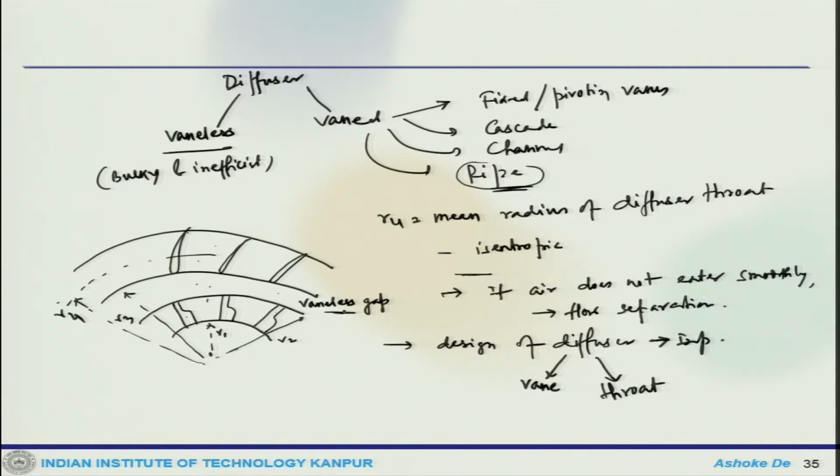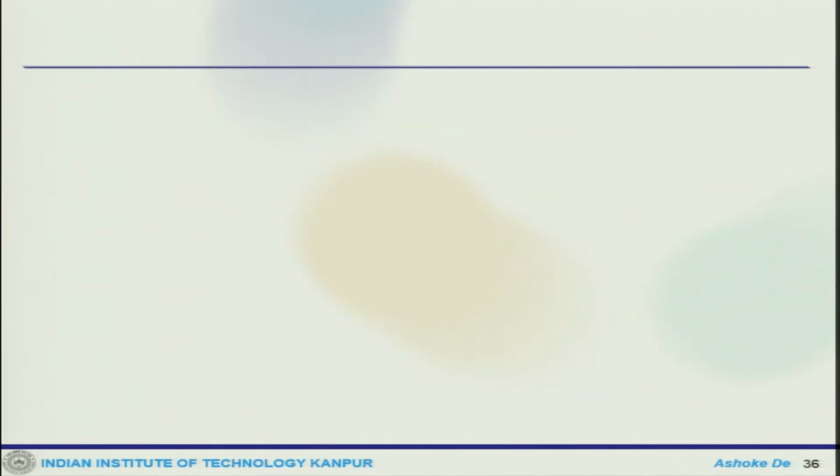in the design consideration. Now, since no further energy is supplied to the air once it leaves the impeller, the angular momentum must be conserved in this vaneless passage, and what is that? You can neglect frictional losses, and the process is isentropic. So, how we will go about it? So, theoretically there should be V theta r is constant.